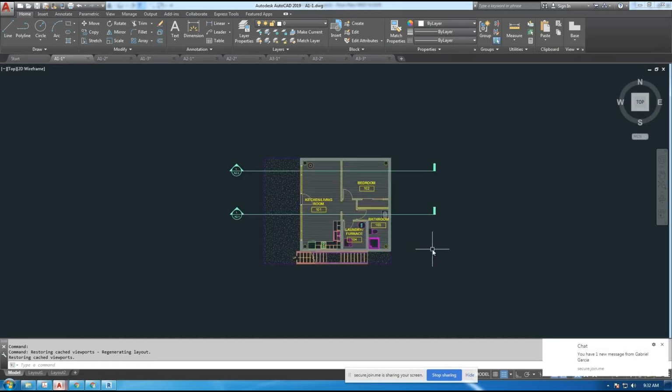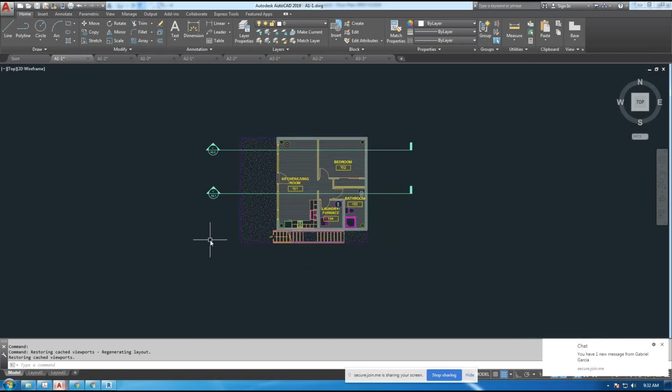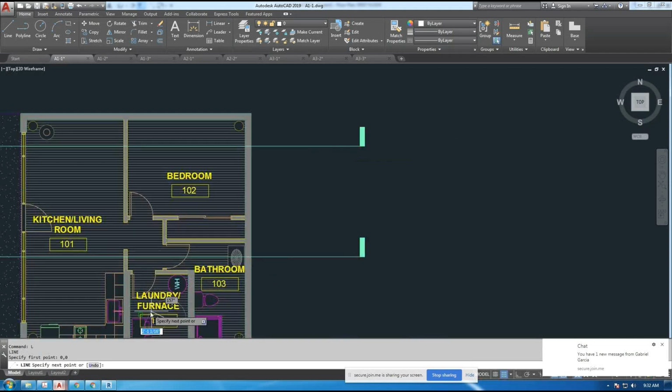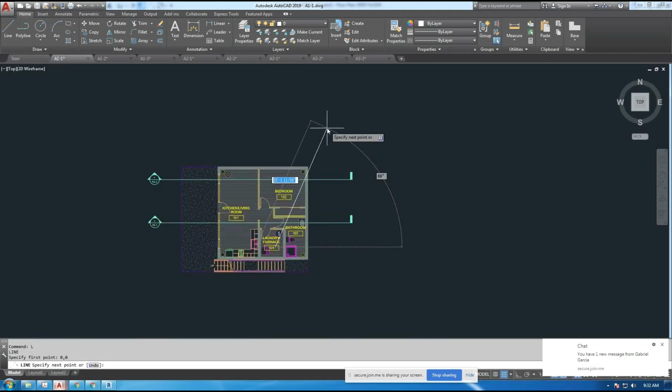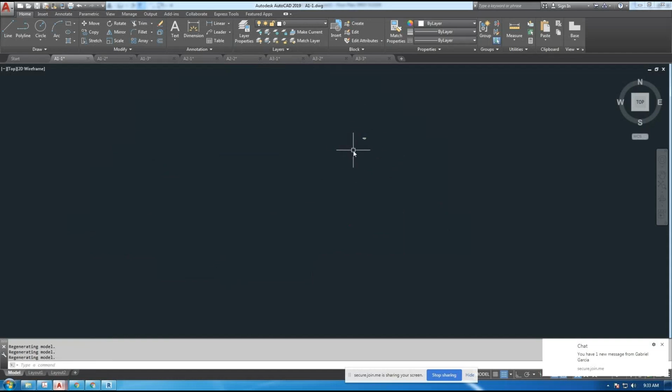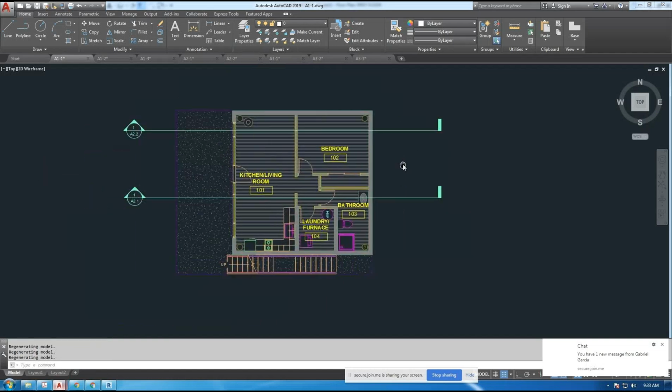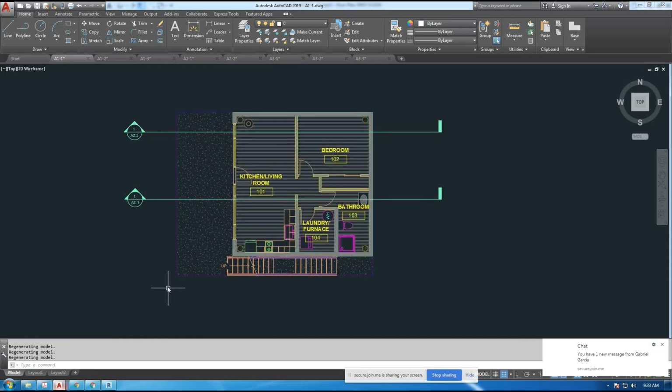If you're using a project from AutoCAD, just remember that somewhere on the screen is 0,0. Somewhere in AutoCAD, there's a point in space called 0,0, and typically you want to draw near that place. That's important for Revit also. So if I draw a line in AutoCAD, L for line, from 0,0, that point in space should be somewhere near your drawing, and typically on the corner of your AutoCAD drawing. That's hugely important, so your drawing doesn't wind up in outer space somewhere, miles and miles away from 0,0 in AutoCAD. So this file has 0,0 somewhere in the middle of the project.